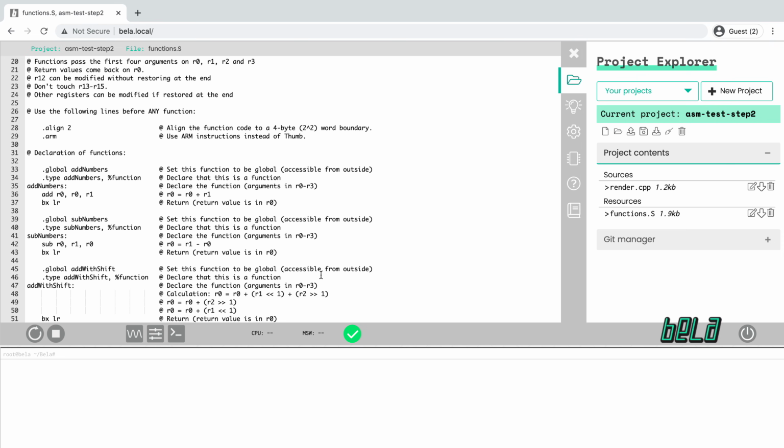I've started out the function prototype here. Notice the .global and .type statements and also the label. Now what I've done here is I've written out the comments for what it is that we want to do. What we need to do is fill in the assembly language instructions that do this. So overall, this line shows us the entire calculation that we want to perform. But this addition of 3 quantities is more complicated than we can implement in a single assembly language instruction. So we're actually going to need to break it down into 2 smaller operations.